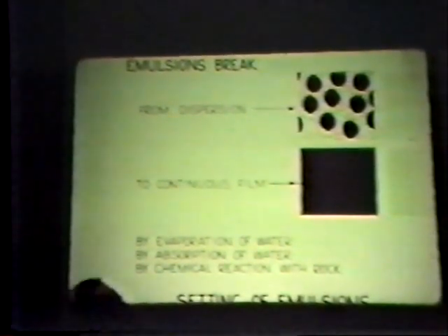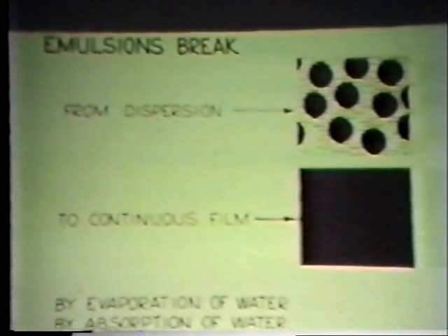Now getting on up to the emulsions and how they're produced, and to give you a hands-on idea, I'm sure everyone's sealed his driveway at one time or another or worked with somebody that did. That's about the closest that you'll have hands-on experience with an emulsion. Those are generally all tar emulsions. Some are asphalt emulsions also. But it's basically a suspension of the asphalt in water with a soaping agent, and that's what keeps it in solution. That's so you can work it or add water to it if you want. Sometimes even mix some sand in with it if you want to make a little patch material on your own.